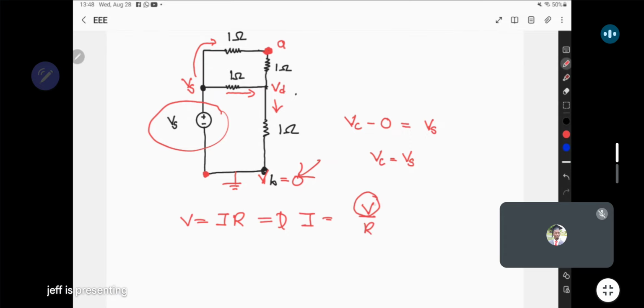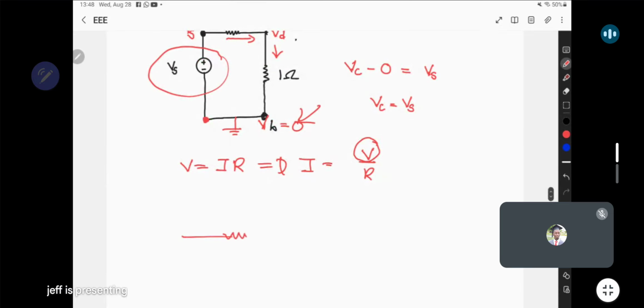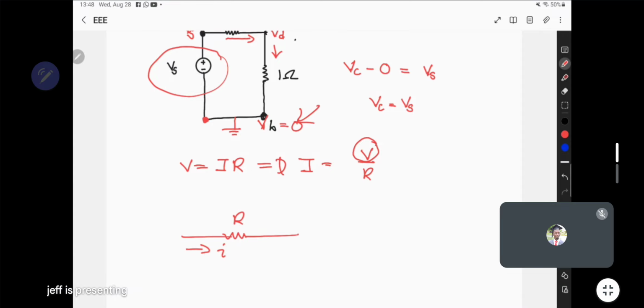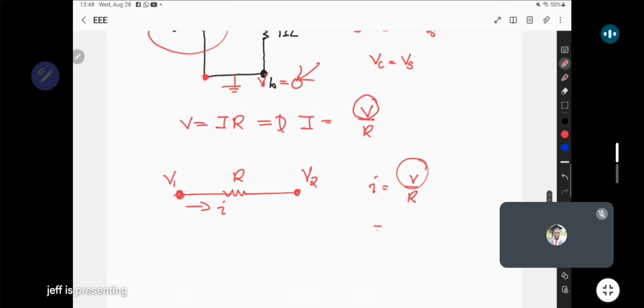But the voltage that is here is the potential difference across a line. So if I have a component like this one with resistance R and the current I passing in it, I can find the voltage it is using by comparing the voltage it was fed, V1, and the voltage that left it, V2. So since in Ohm's law this is V over R, the voltage drop across that resistor will be equal to the voltage it was fed, V1, minus the voltage that left it,